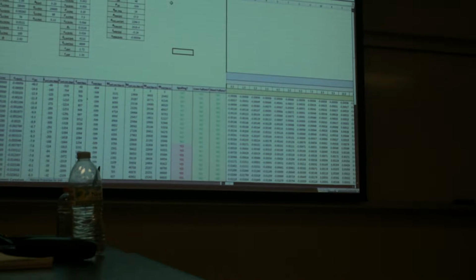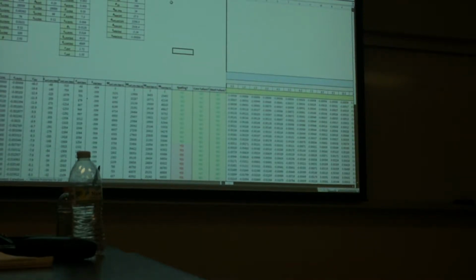I'm calculating that because I want to know what's the initial strain on the cross section to start out. Because this section doesn't have zero load. It's not this section floating in space. It's got a load when there's no curvature on there, right? You've got some dead load on your column. In this case, our dead load is equal to 600 kips compressive force. So you've got some initial load. That initial load is going to cause initial strains.